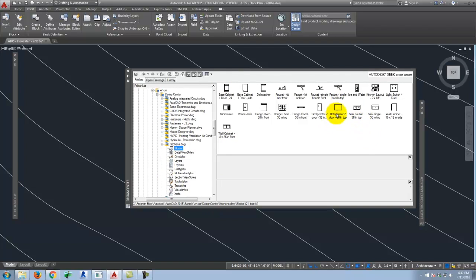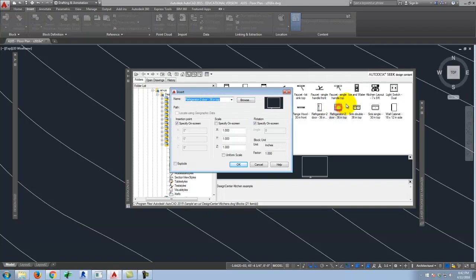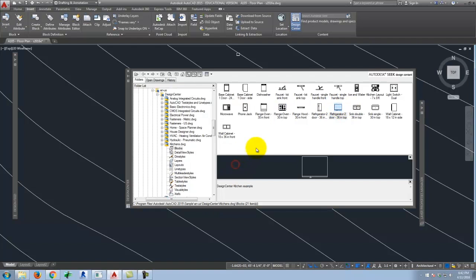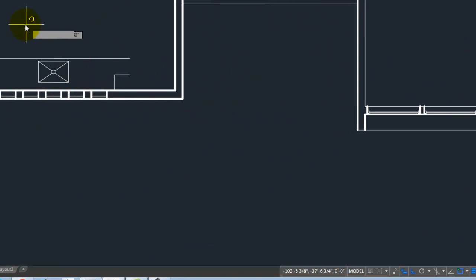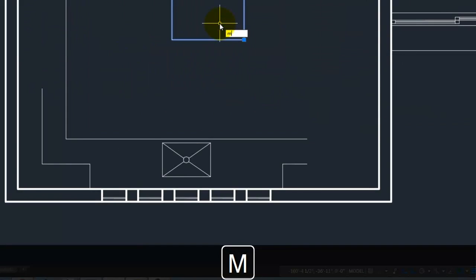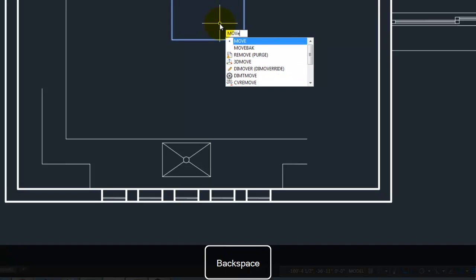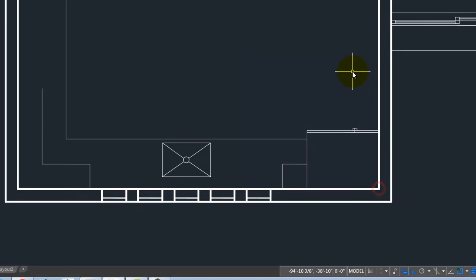So here's one that's called a refrigerator. And I can double click that refrigerator. And I can say OK. And it will then let me drop it into my building. Say right there. Now I want to change the rotation so that it's in the correct orientation. And then I'll go ahead and move it from here to there so that it's part of my kitchen. Okay? So I can do this with a stove. Right? There's a variety of objects that I can continue doing.